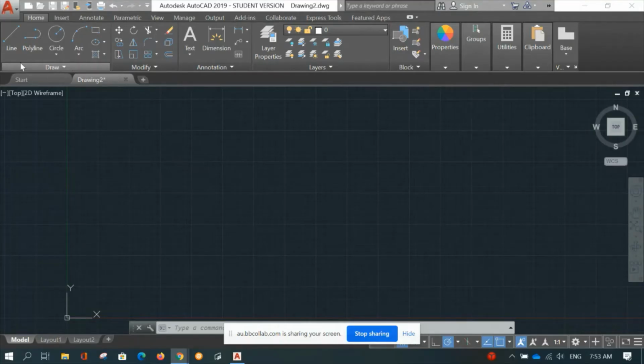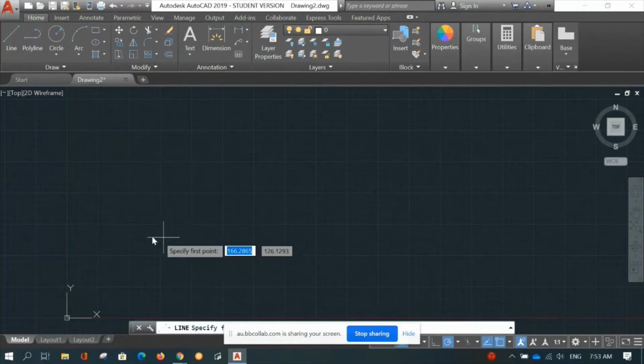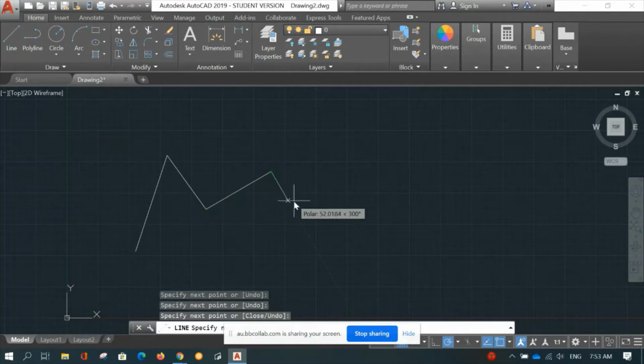I'm going to show you how we will use the dynamic input function in AutoCAD. You can activate the dynamic input by pressing F12 on the keyboard. For example, let's say we are going to create a line. That's a single line, right? Okay. So the normal cursor will be empty. If you're creating a line, nothing appears except for the polar tracking or the distance.